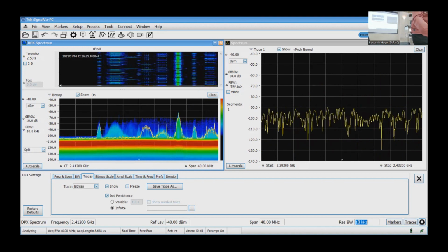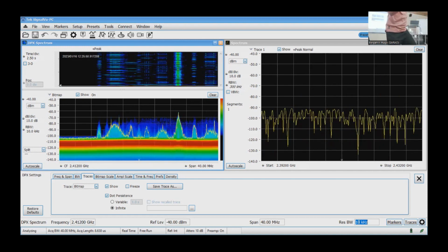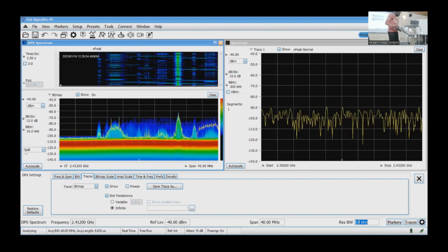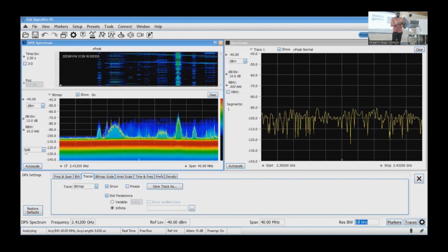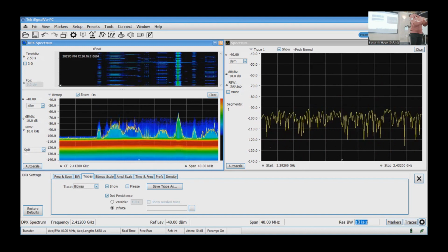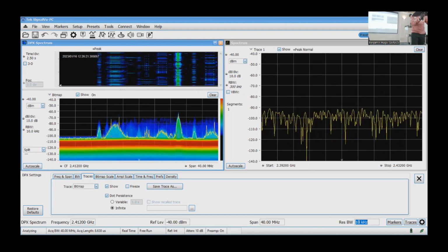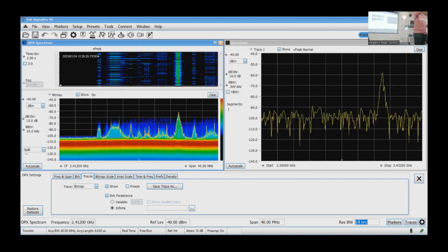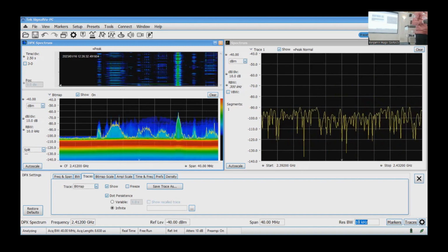So then you go to a unidirectional antenna, and this is a log periodic antenna. Let's say I've done my scan and identified specific frequencies. Then you attach this one here, and if the signal is strong in this particular direction, you see the amplitude increase. If you shift a little bit, because this is unidirectional, the amplitude will reduce, so you know it is not in this direction. You keep on going, and that's what you call direction finding of RFI. You move until you see where it's strongest.